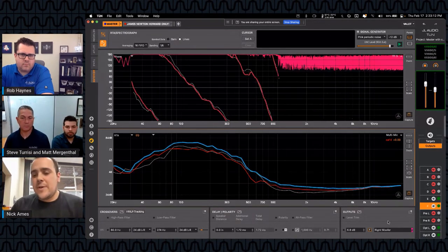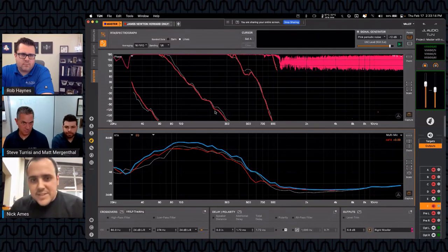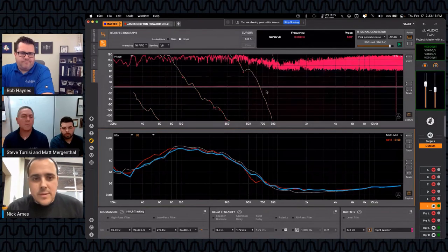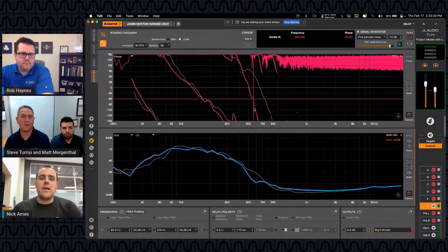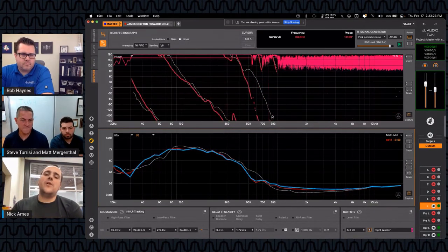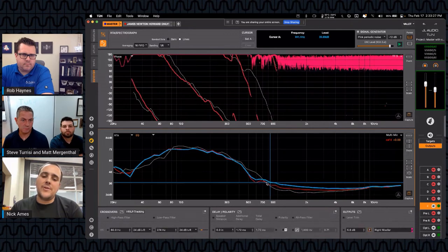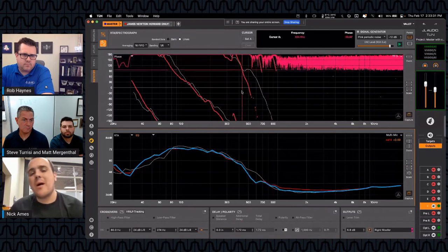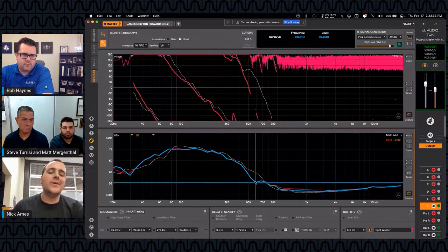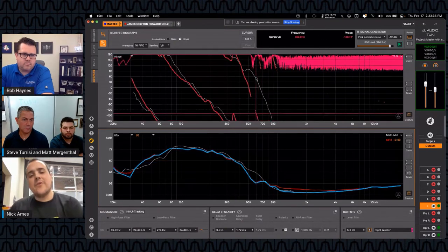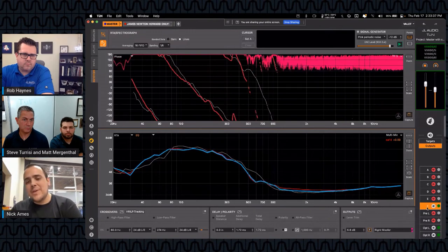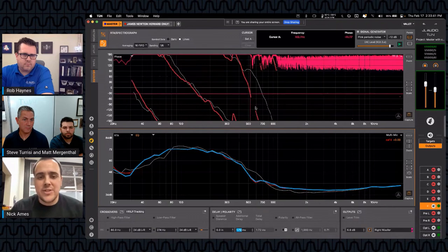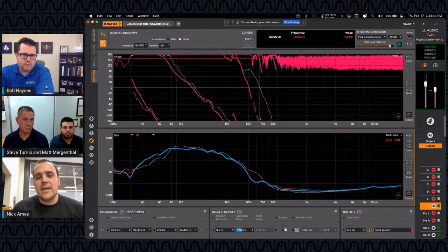So this area up here that you asked about a minute ago, let's take a look again at that. I guess it was this one. It was like from 500 to 900. Yep. So right up here at around 900 hertz or so, that's when we're getting close to the noise floor, so I would probably say that really doesn't matter. However, you could back a little bit of delay off of this, and that would move that red trace closer to the gray.